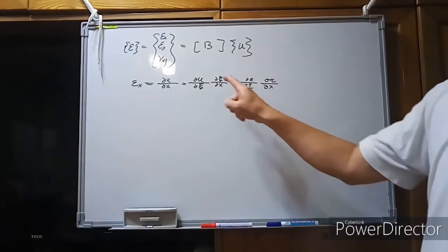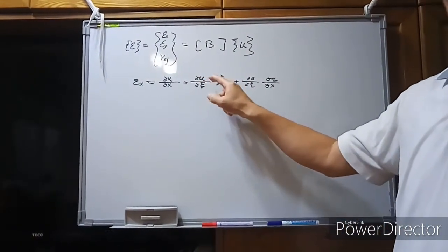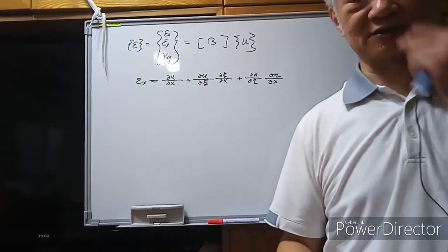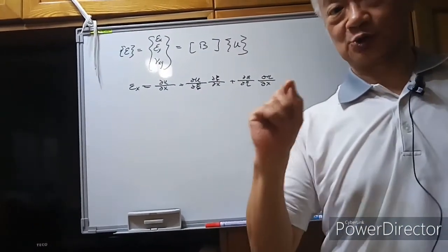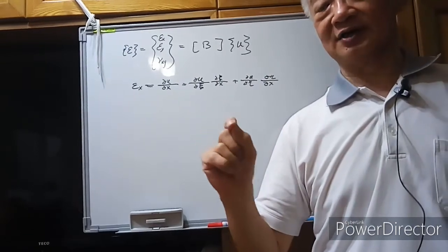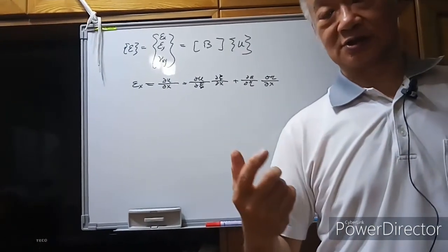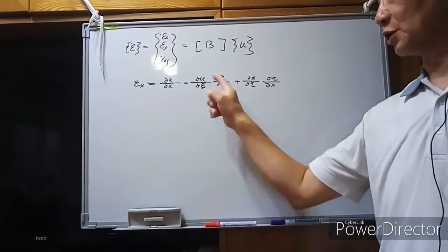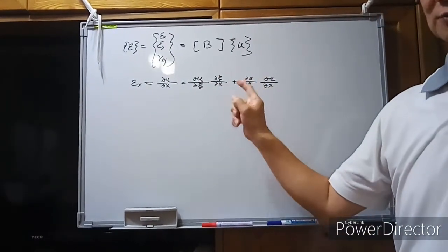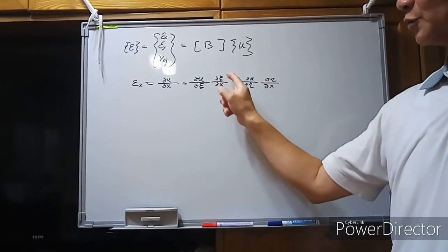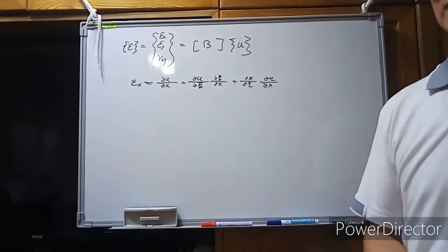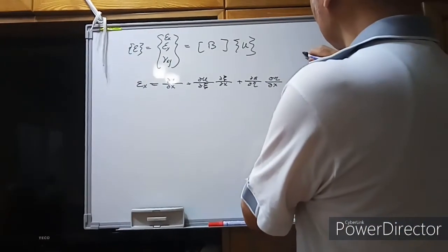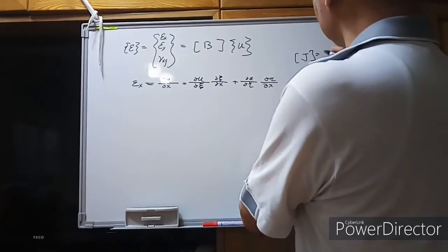displacement functions. Since we know the U functions, although they are still functions of the assumed nodal displacements Ui and Vi, we can still use the assumed values to calculate the partial derivatives of these two terms. And how do we calculate the partial xi to partial x? Usually we solve the J matrix first.